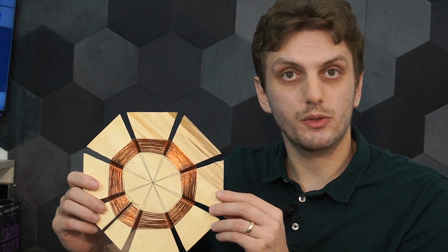On the other hand, with the spiderweb shape, the field is far more spread out, so you don't have a very linear field, but rather it spreads out all over the place. And you have this sort of inductor commonly used with things like wireless charging or induction heating. And that is because you don't want to have a single position in space where you can charge your phone. You want it to work wherever you put the phone onto the coil. So for this application, since we don't want to have a very, very precise alignment between our receiver and the coil, we can go with this sort of inductor shape.